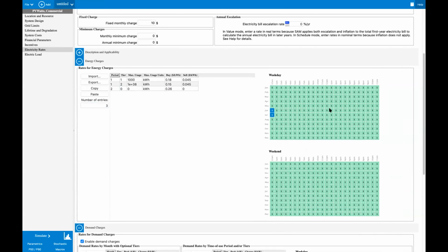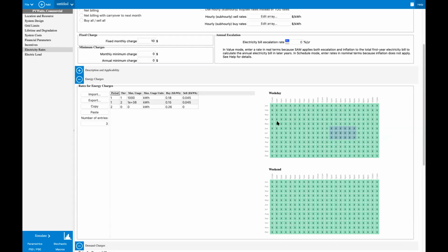June, say 1 through 6 o'clock, June through August. You could just select that, type the number 2, and that's going to give you a different rate based on that period. So you can get very detailed with your time of use rates, whether that's seasonal or hourly during the day, and construct some pretty unique rate structures within this, which really gets more accurate as we estimate the value of a unit of energy. So I'm going to put that back to 2.